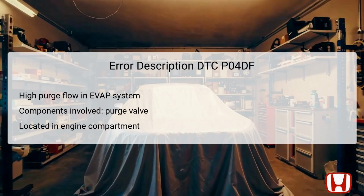DTC P04DF specifically indicates a high purge flow detected in the evaporative emissions control (EVAP) system. The main component involved in this scenario is the EVAP canister purge valve, which is responsible for regulating the flow of fuel vapors from the EVAP canister to the intake manifold. This component is typically located in the engine compartment, connected to various hoses that transport air and vapor.